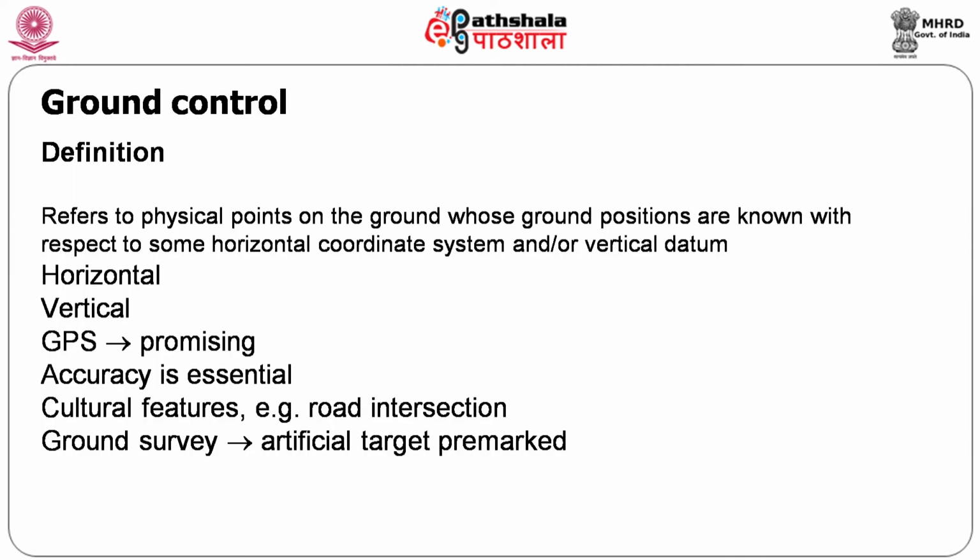So, the aim is to plan the photography, take the photographs with control points, and then perform whatever is required in terms of correcting it, identify the objects, find the required features on the aerial photograph, and finally create a map of it.